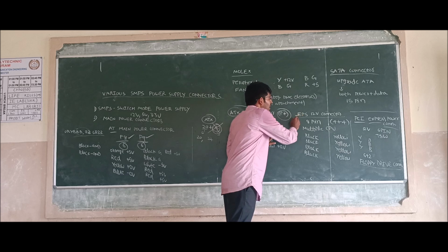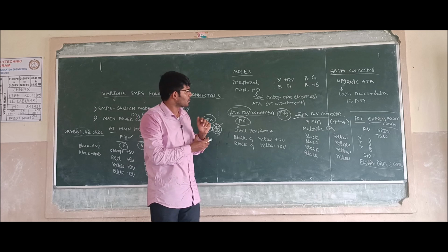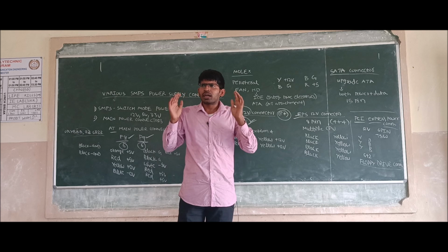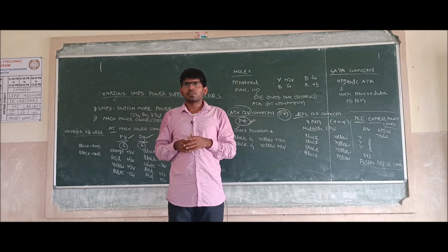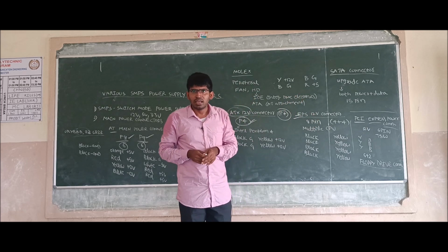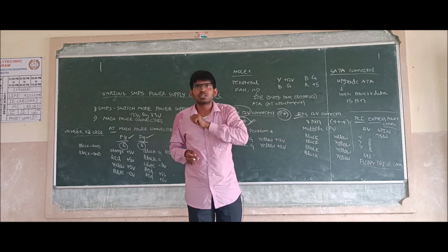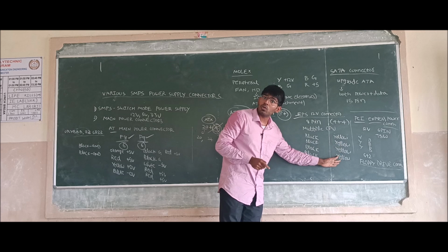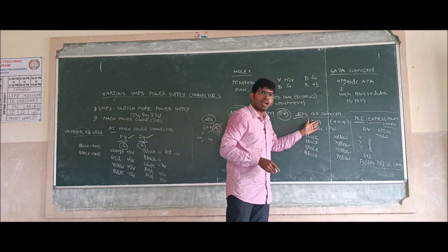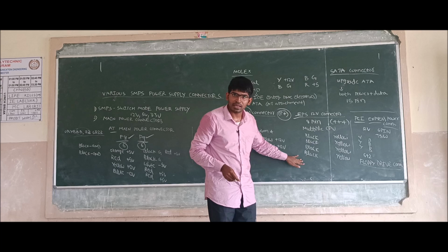Next we are using the EPS 12 volt connector. Sir, why this EPS 12 volt connector? Initially, I want to turn on multiple processors at a time. At that time, they used this 8-pin EPS 12 volt connector. As we already discussed, we give this to power up the processor. Processor means definitely it requires 12 volts. But we are saying multiple processors. So here we have an 8-pin connector, 4 yellow and 4 black.